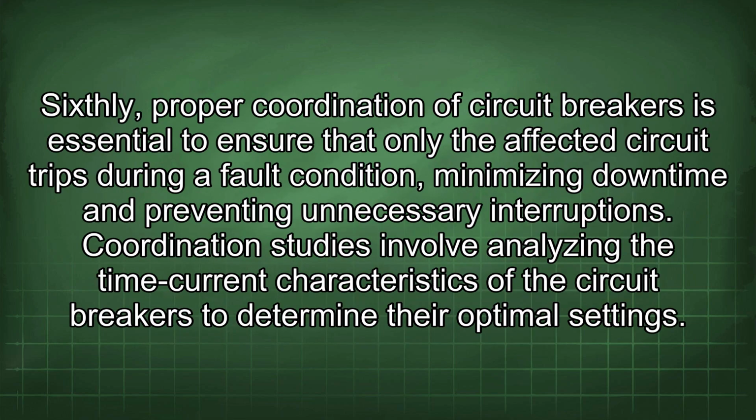Sixthly, proper coordination of circuit breakers is essential to ensure that only the affected circuit trips during a fault condition, minimizing downtime and preventing unnecessary interruptions. Coordination studies involve analyzing the time current characteristics of the circuit breakers to determine their optimal settings.